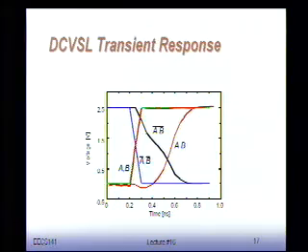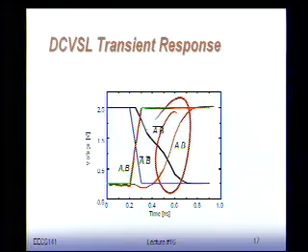Remember that node, I turn that NMOS network on, and I'm starting to pull that node down. And it's hard. The system is resisting me. And the other node doesn't do anything initially. But when I get to a certain point, I start turning on that other device. This node starts to go up, and then suddenly it switches and it goes really fast here. So this is an example of that feedback action that you have to overcome. When you overcome it, it goes quickly.